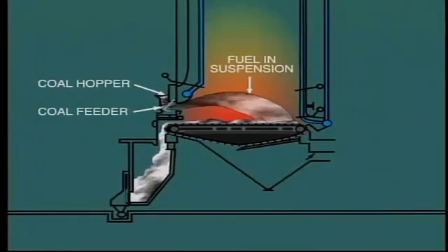The remaining coal eventually falls to the grate, where it continues to burn in the conventional traveling grate manner. Ash is finally dumped into the ash pit as the traveling belt turns. This type of spreader stoker arrangement is sometimes used for burning waste material.